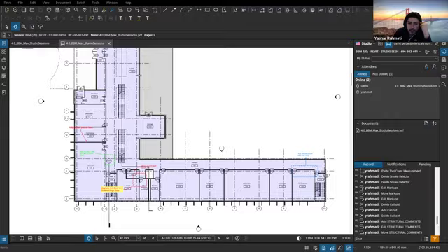With Smart Review, can you add your own comments to it and share? Smart Review automatically generates all the comments. At some point, if you want to add, you can use manual markup adding as well. But once it's added to the platform, it's pretty much a dashboard with all the markups, where we can just change the priorities. At that point we cannot add any markup unless you open up the file in your Bluebeam Cloud environment and add the markup using the markup functions in Bluebeam Cloud, because at any point you can use that plan to add markups anyway.